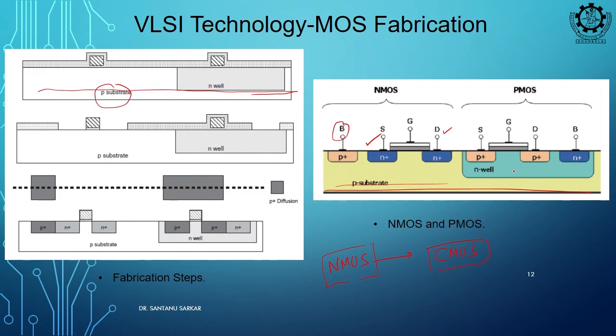So, similarly for NMOS also we will be having a bulk or body, right. So, can you tell me for NMOS what should this bulk be connected to? Ground. Why? Whatever you said is right, that it should be connected to ground, but why? PN junction reverse bias, otherwise what will happen? Leakage current will flow, that will flow to where? To the ground line.